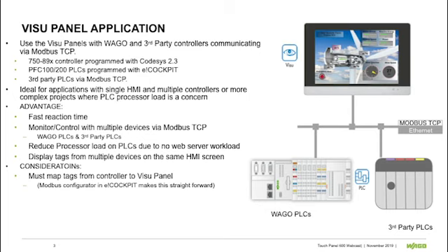A consideration of using the Visu Panel is that you must map tags from the PLC to the tags in the HMI. However, I would note that the eCockpit software offers a Modbus configurator to simplify this process.